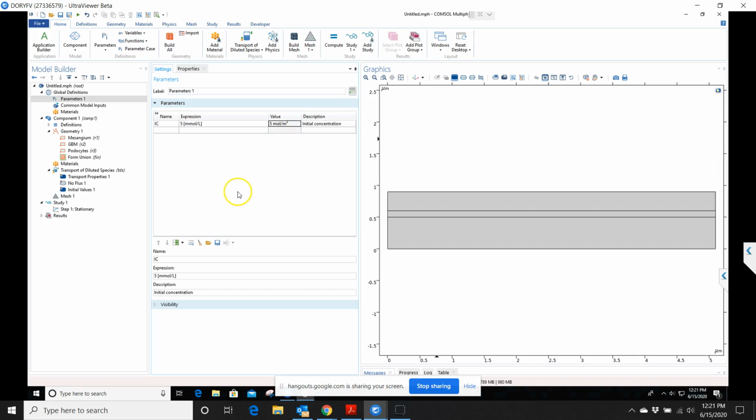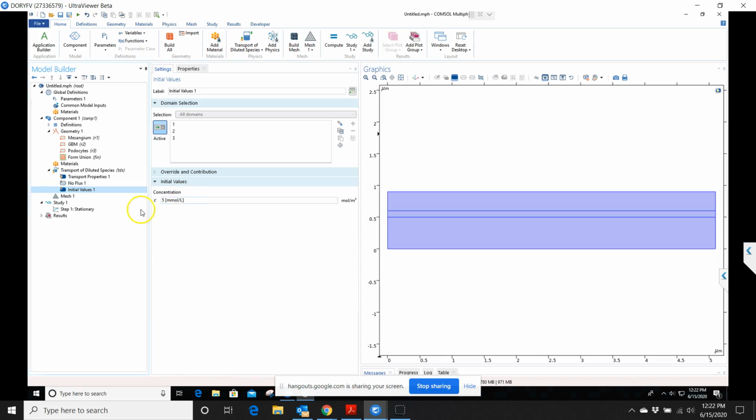Yes, okay, so that's the right unit conversion there. So we actually could have just put 5 here. But this bracket thing is you telling COMSOL that you're putting in your own units, and it will automatically convert to the standard that the software uses. So you don't have to do it on your end. You can just tell it what units you're putting in, and as long as it's compatible with what you're dealing with, it'll automatically convert.